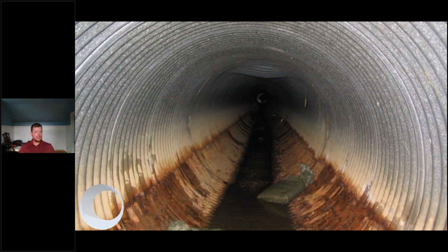And so from a design standpoint, again, when we're concerned with the resiliency of the hydraulic capacity of these pipes, we want to make sure that we're taking all of those future changes into consideration. So with the concrete pipe, we need to consider the entire length of the design life. With the metal pipe, the same thing is true. So if that flow line is going to become rusted or completely missing, that's going to change all of those flow capacities.